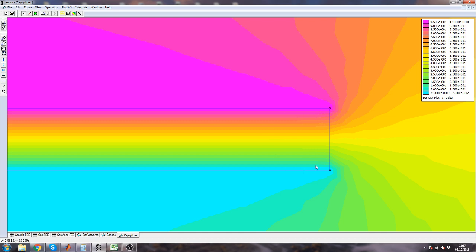If the FR4 region was quite small and it was in fact large compared to the fringing distance, then we'd start to worry about whether this applies or not. Anyway, in practice you don't make capacitors that are a metre square, and you don't really make capacitors that only have two electrodes. There are two electrodes, but they are constructed in an interdigitated fashion so that you can have more than one. You can have anode, cathode with a dielectric, and then another layer of dielectric, and that would have an anode, dielectric, cathode, dielectric, anode.